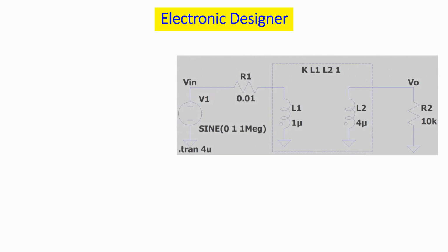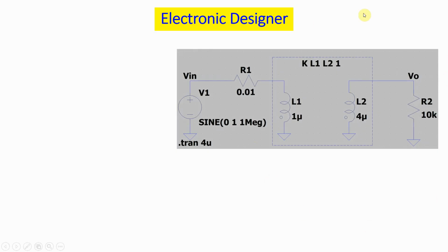This is Ehsan, and in today's video we're going to learn how to model this transformer. I'm using this simple circuit to show how to model a transformer in LTspice. This box where you see L1, L2 with this note here models a transformer in LTspice.